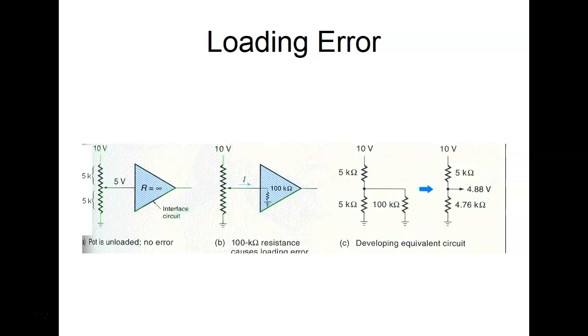We're not going to have any problems because we're going to use a 10K pot. I think we're using a 10K pot in your multimeter. We can assume it's got what on your volt scale? Probably around 10 megohms. But you can measure that. How could you measure that? How'd y'all measure it back in DC when y'all did your meter certification? You put the meter on volts, and then you took an ohm meter and you measured across that thing, and you measured the input resistance of your meter. Yeah, it was 14. I think that thing measured around 14 meg.